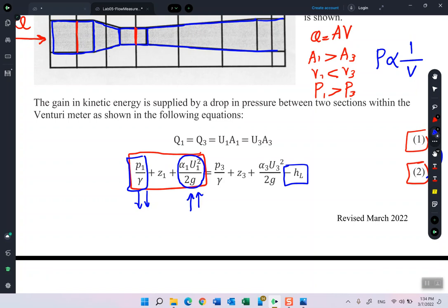You should be familiar with the head losses term from the lecture, but in case you are not, the head losses is simply something to consider the energy that is lost within the pipe. Of course, if we have a pipe and water is flowing inside it, it will have some friction with the wall. This consumes some of the water energy, and this energy can't be converted to any kind of potential or kinetic energy. This energy is totally lost. I can't use it anymore.